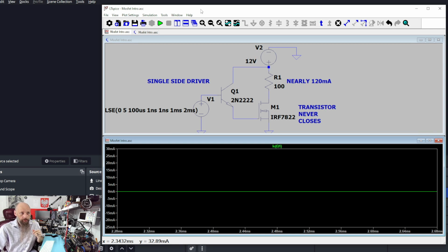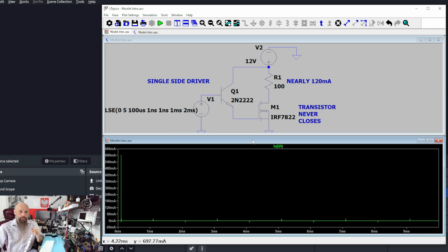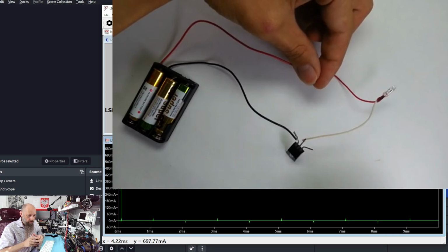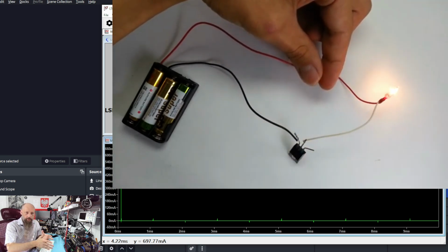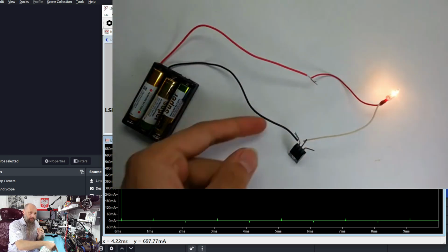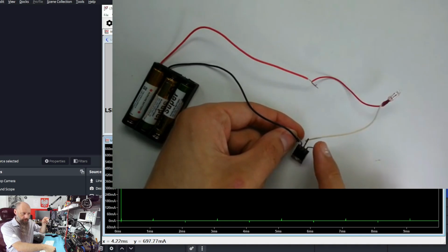So that is important to know, especially when you're measuring in circuit. Remember that if you touch the gate of the MOSFET with your finger, you can open it. You can charge the gate just by using your finger. There is a great example that you can find on YouTube, connecting the MOSFET and touching the gate, and then touching the positive and negative.